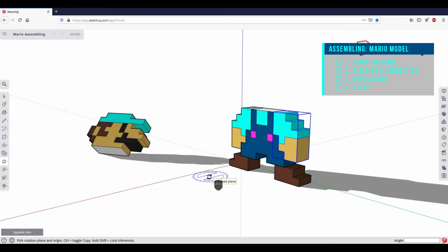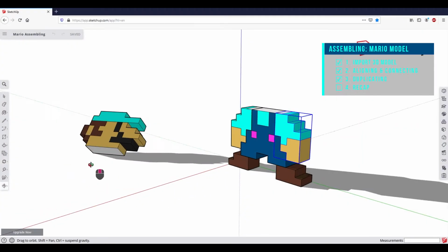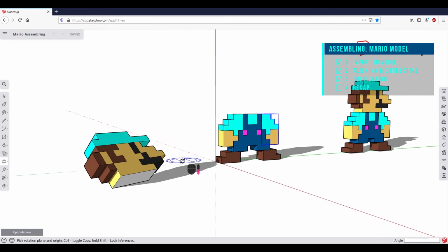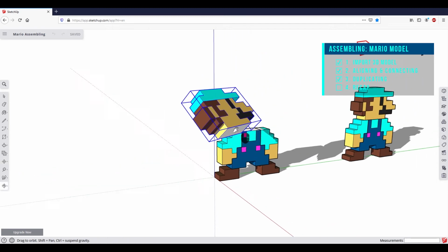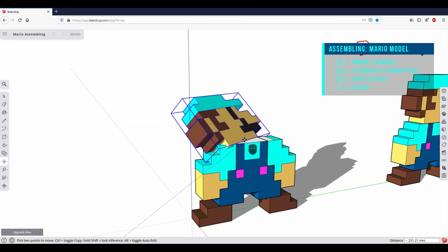And this brings us to the head of the whole thing, which is twisted in all axes. What a mess! Let us first connect the head with the torso, so that we can see better how far the axes have to be rotated. So take the Select tool with the spacebar, click on the head, and then press the M key to move it. Since the head has to be placed in the middle of the torso, we grab the head at the center and let it snap to the back center of the torso.